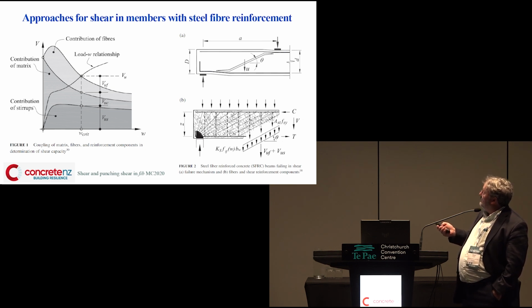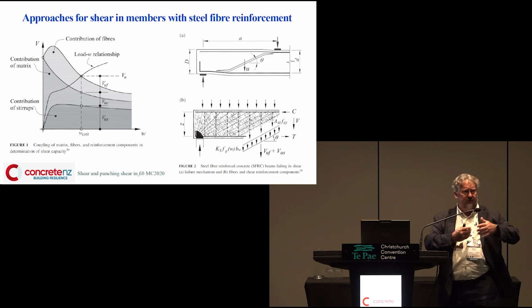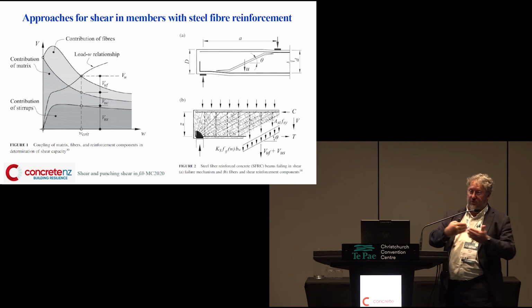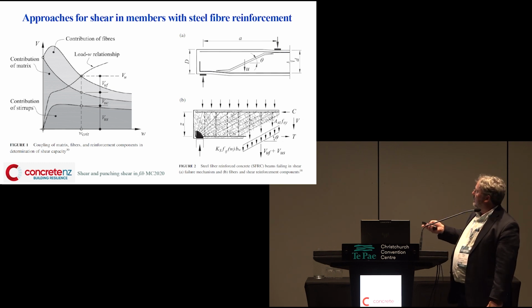One thing to note, so plasticity has this movement downwards, and the movement of that crack opening, which defines the crack width, fibres align with the direction of movement. They're very flexible, and the stress aligns with the direction of movement, not normal to the crack, as you'll see in many papers.